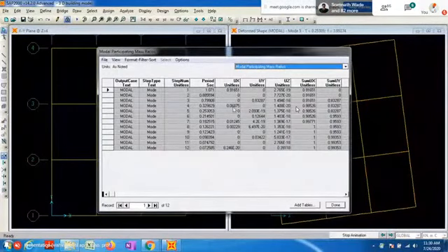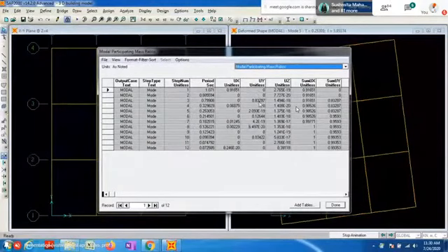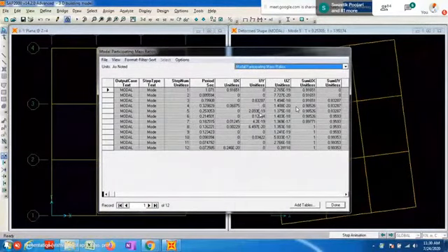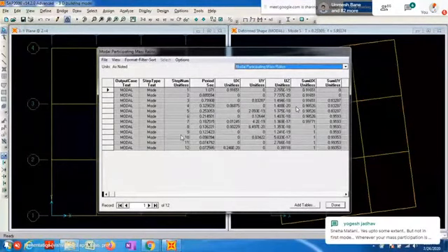The fourth mode has time period 0.32. Next, along the Y direction, this is the first one, with time period 0.79. The next translation mode has time period 0.20. This is required later in the time history analysis while defining the damping.